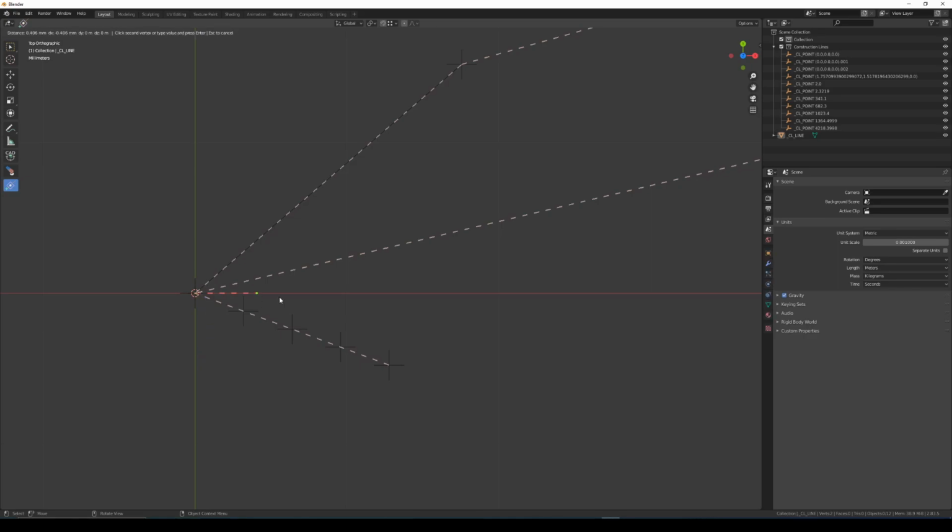In a similar way, another feature from previously is if I start to draw an arc or a circle, I'll drag this out, you can use that same technique of holding control down and rolling the mouse wheel to increase the segments. If you look up in the left hand corner, this is just controlling the number of segments using control on the mouse wheel. You can still use just the arrow key, but I think it's probably easier to use the mouse wheel if you have one, holding control. So that was from previous versions, but I wanted to show it there.